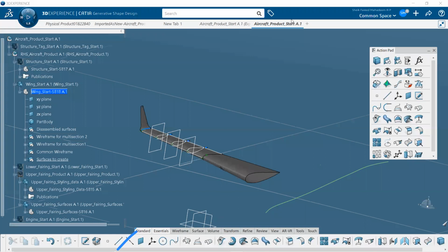And finally we created two boundaries. We used the three created curves and the already created edges of the wing, and we used the boundaries as a guide, and we generated the multi-section. Then we added all the surfaces together to create the complete wing.